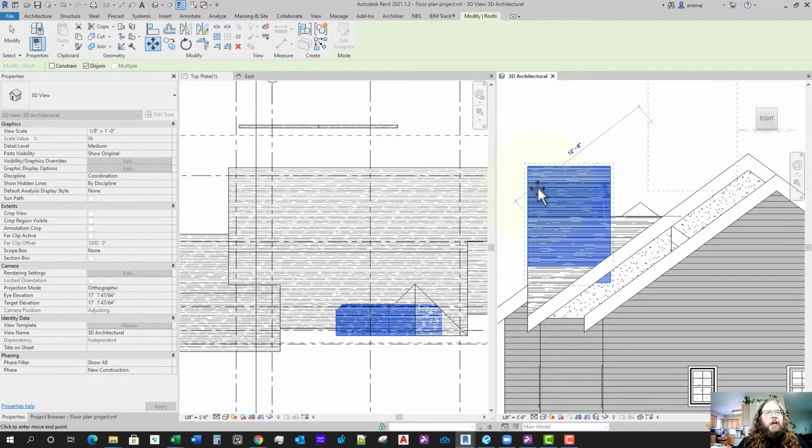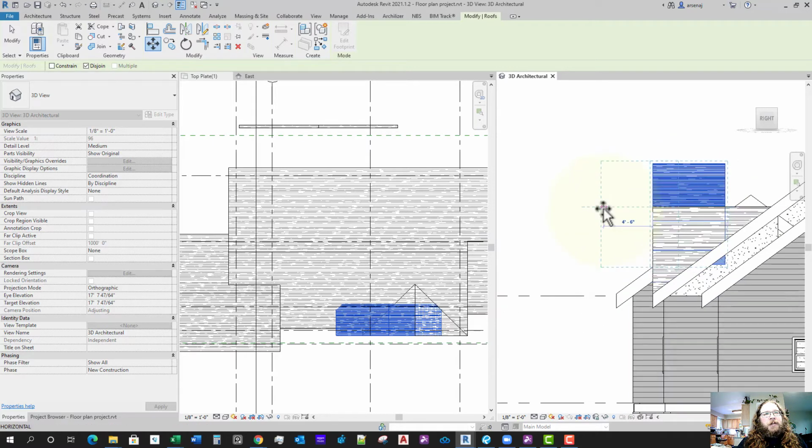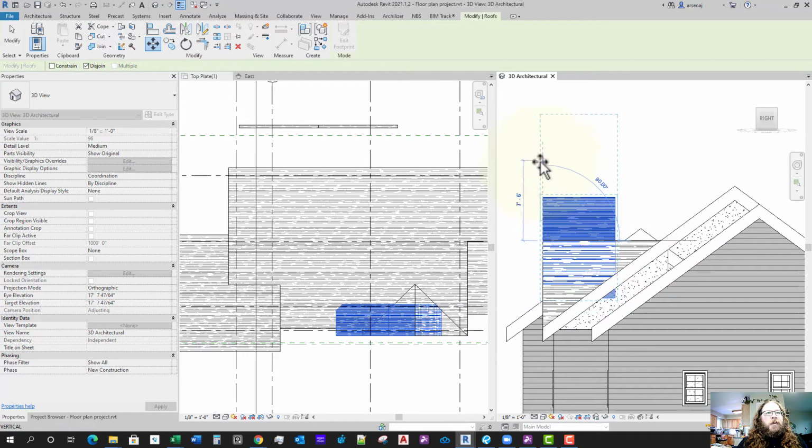So when you're in the move command, if you move it left to right, you can kind of see how it gives you the little angled degrees if you're off angle, but if you're on a 90-degree angle, or a 0 actually, or 90, you can see it snapping to it. If you're 0, it won't give you any angle, but if you're moving anything other than 0 it gives you an angle. You can just move it over to the right, make sure it's not angled, and then you can enter in any number to give it a dimension to move it back.